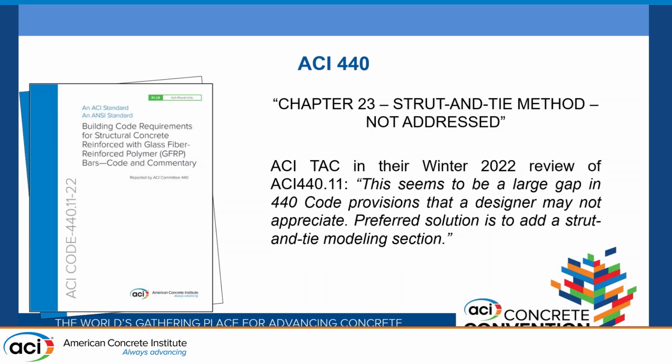In ACI 440, Strut-and-Tie, Chapter 23, is not addressed. When this was brought up in the winter 2022 review of ACI 440, the TAC committee said that this seems to be a large gap, and that the preferred solution for designers would be to add a Strut-and-Tie modeling section. The response from Committee 440 was that they do not feel comfortable due to a lack of research that would enable them to include Chapter 23.